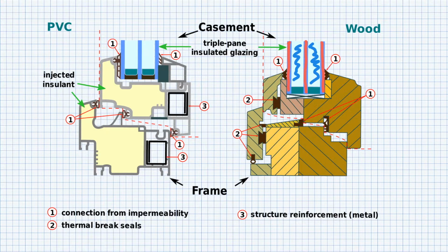The other advantage to this is that you can also place a layer, maybe 5 atoms thick, of silver. This is called a low E coating. Typically it's applied to either the second surface or the third surface. What that means is, the first surface is the outer pane, and then the second surface is the inner side of that first pane. So by putting it on the second surface, it protects it from the outside elements, but then it also allows you to reflect it back before it gets in to this dead air chamber.